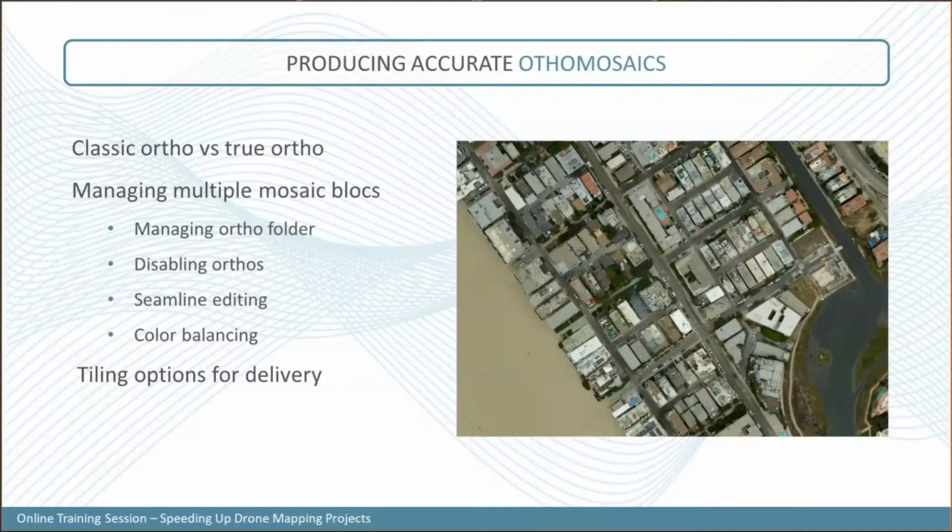Typically, the classic ortho gives better visual results for mapping products. It's highly dependent on the quality of the DTM, but we usually recommend generating the DTM and then the orthos from the DTM if you want great results for your mosaic. The Ortho Mosaic is basically a two-step process. First of all, you need to derive individual orthos from the imagery. Each individual image will have its own file, compressed or not, and then we take those orthos to derive a seamless and color-balanced mosaic.